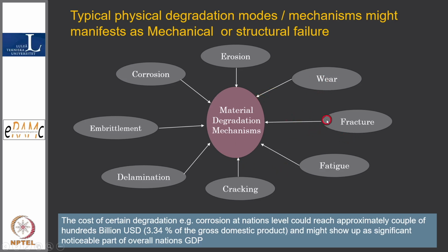Fracture, I would say, if we want to predict fracture, a lot of uncertainties are associated with the model itself, which is so complex. It has so many lifetime loads. So what is done in the plant is something called in-service inspection, which is done to address corrosion, fracture, this kind of issue, and then you try to predict the life and symptom.